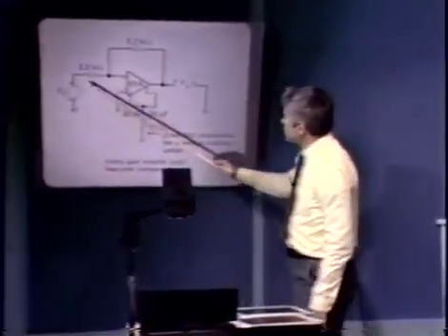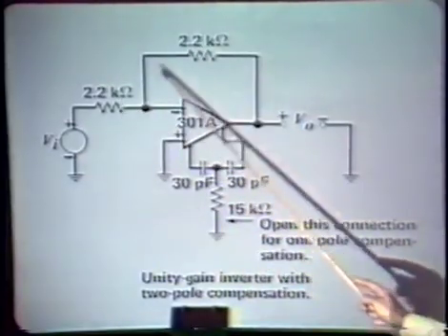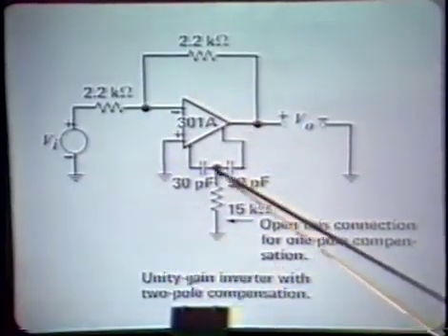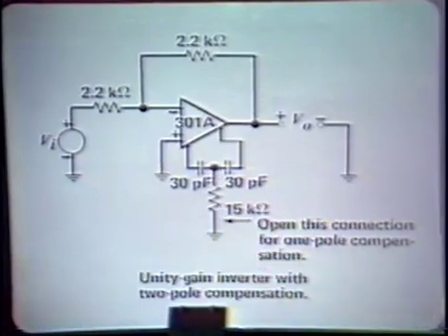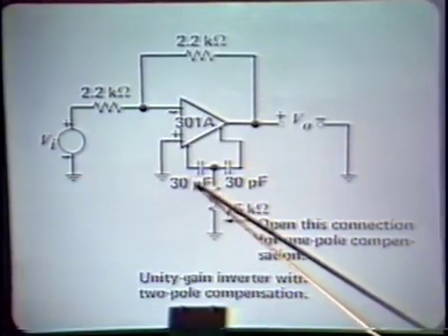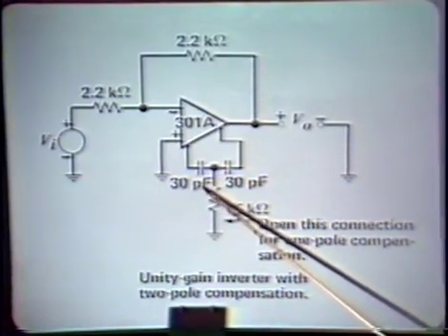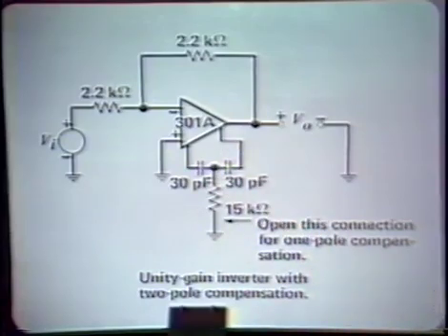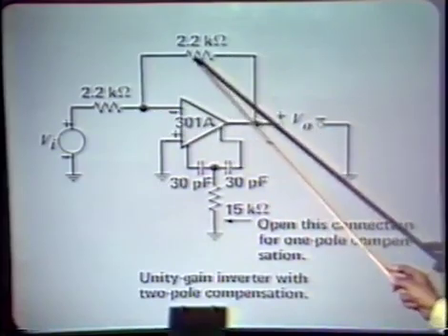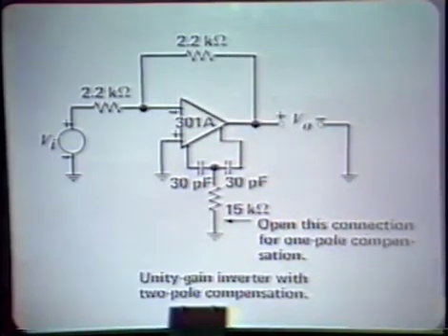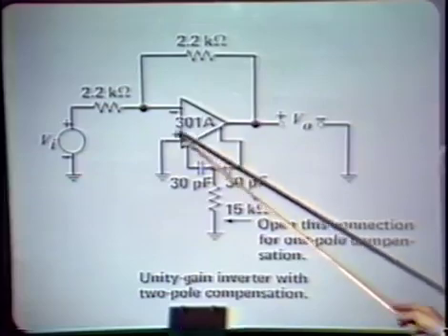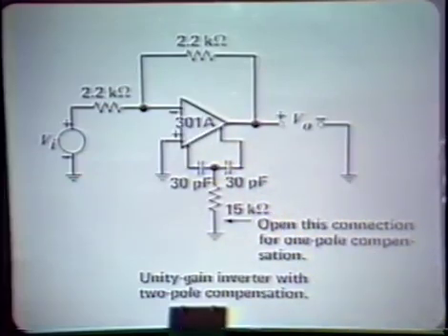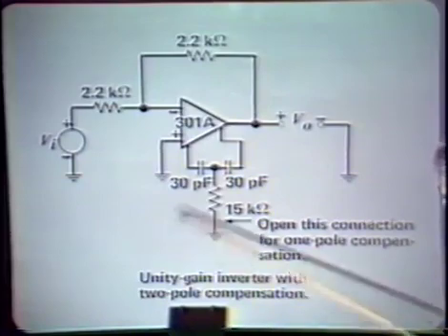Here's the configuration. We simply have an equal valued input and feedback resistor. We have the T network that does compensation. In this case, we chose elements in the T so that the unity gain frequency in the amplifier is about 1.5 megahertz. The 2-to-1 attenuation provided by the feedback network forces overall crossover at about 1 megahertz or so.